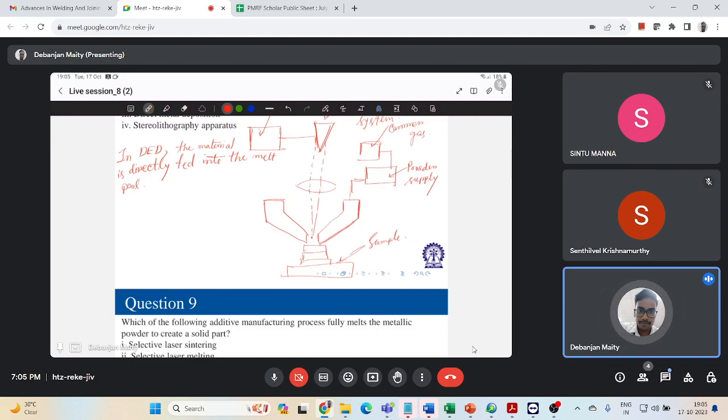Now, the methods of DED can also be based on source of energy. So again, you have laser powder directed energy deposition, laser wire directed energy deposition, arc wire directed energy deposition, and you can have electron beam directed energy deposition. Those are based on changing your power sources, right? The only energy source possible for the powder feed mechanism is a laser. As for the wire feed mechanism, the possible energy sources are laser, electron beam, and electric arc. So those things are there, right?